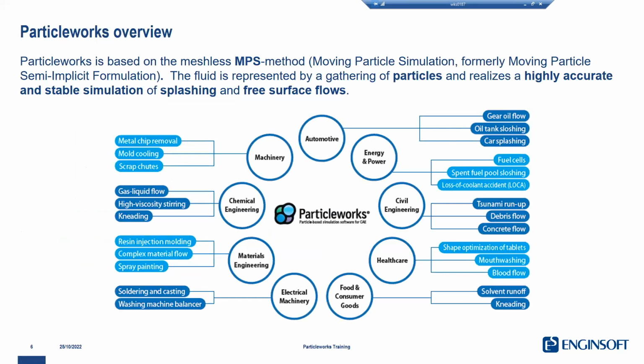So what is Particleworks? Particleworks, as I mentioned, is a CFD tool, a computational fluid dynamics tool based on the meshless moving particle simulation approach. This approach doesn't require, and we will see in a few slides in more detail, the generation of the computational mesh that you have in conventional CFD. So you can take the CAD as it is. From the designer, you take, for instance, the transmission, or the engine, or the piston, or the e-motor, and you directly transfer the geometry to your simulation interface.